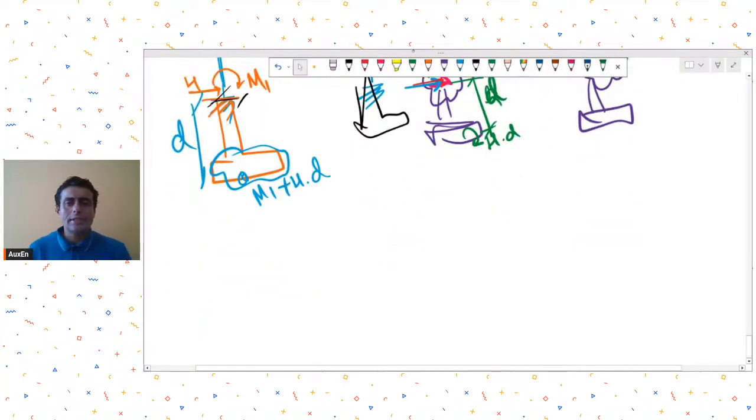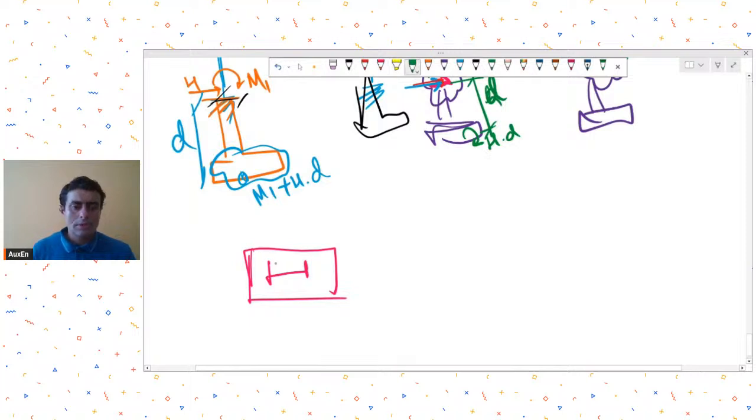Now in steel sections, if I talk about the I section, generally if this is the plan view, and let's say the moment is about this axis, to provide pin support they will provide bolts very close to the neutral axis, just holding down bolts, and this is an approximation through which they can assume a pin like behavior. I'm using the term pin like.